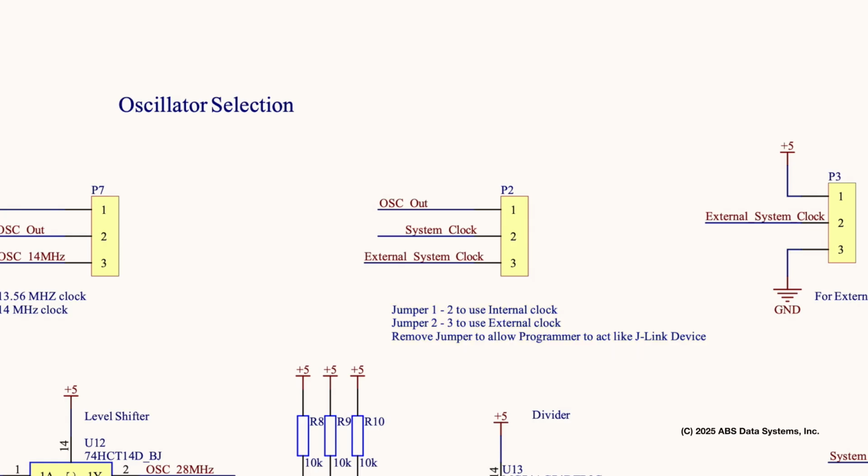One more thing, since one of the sources is external, you could drive the system clock with a toggle switch or a push button switch to single step the CPU. Or you could set your function generator to run at any speed from 1 Hz to 14 MHz. If you use a toggle or push button switch, be sure to create a debounce circuit or you'll get unpredictable results.